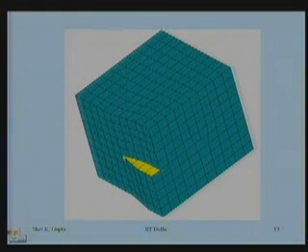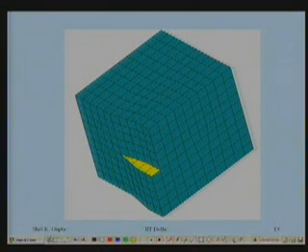So configuration here is that of a screw, configuration here is that of an edge, but in between you will find a mixed component, no? Right, very important thing is here, right. So my dislocation line is going like this, coming here.